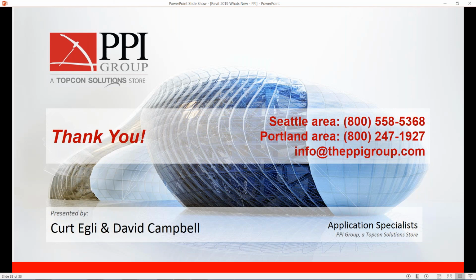Oh yeah, she's been using temporary. So one of the ways is if you click the sunglasses, if you do use the temporary, you'll see down towards the bottom that it says apply hide or isolate. So you can do it that way. It will keep the hide there, or using that EH for element hide or VH for category hide will also keep them hidden. Now you can hit that little light bulb next to your sunglasses to find all of your hidden items there.